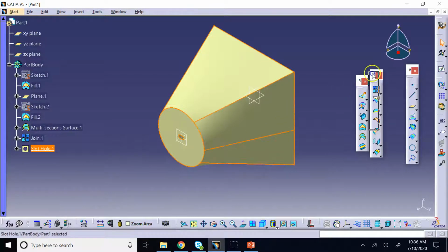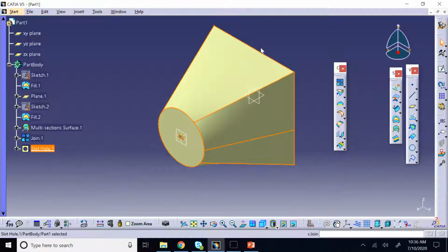So if you go to this operation toolbar here, if you go down here, the second item from the bottom, if you look at it, you can translate the surface, rotate the surface, do a symmetry. Now remember, symmetry is different than mirror. It transfers it from one side of a plane to another side. You can scale it, or you can do affinity. And if you remember, affinity is a non-uniform scaling. So you can basically scale it in different directions differently, right?